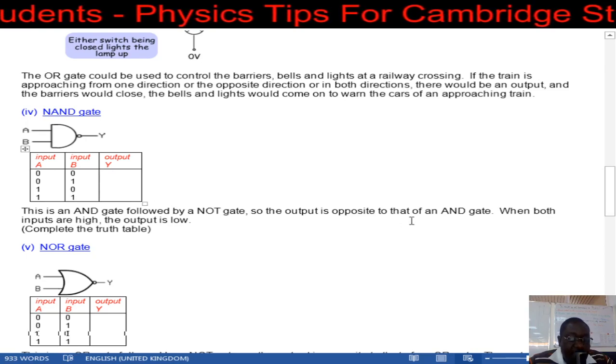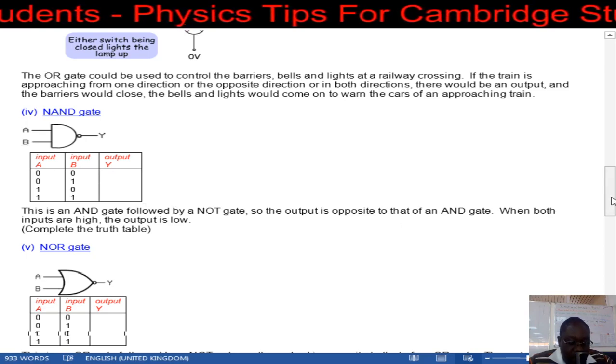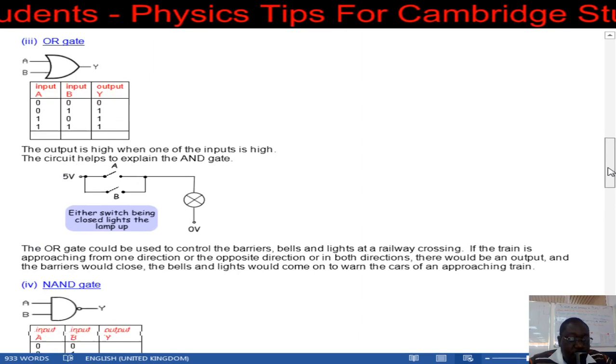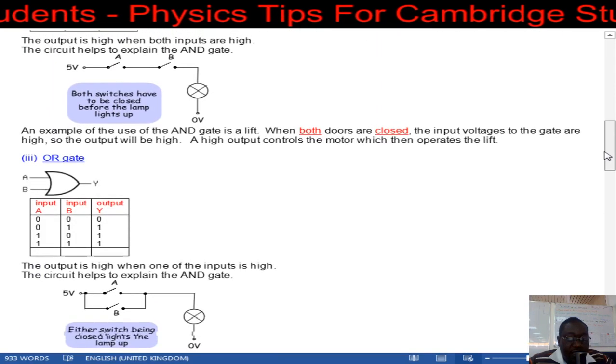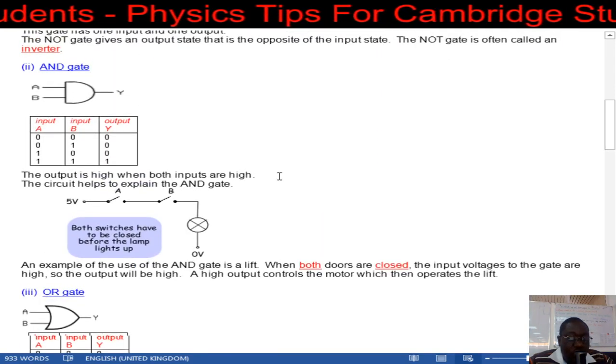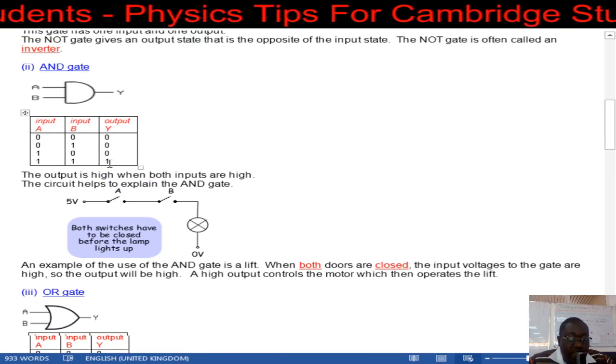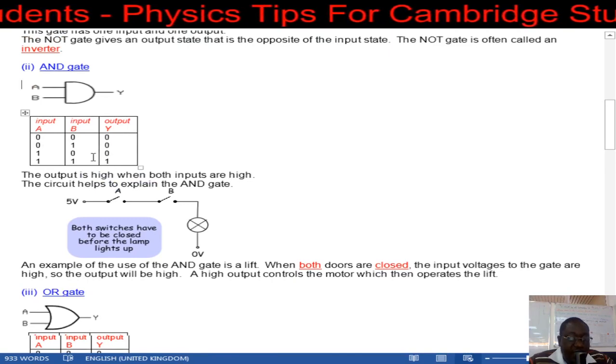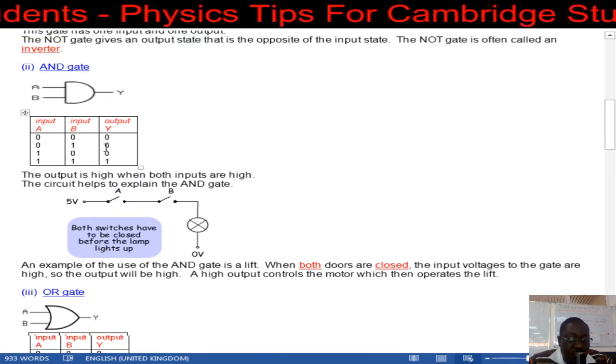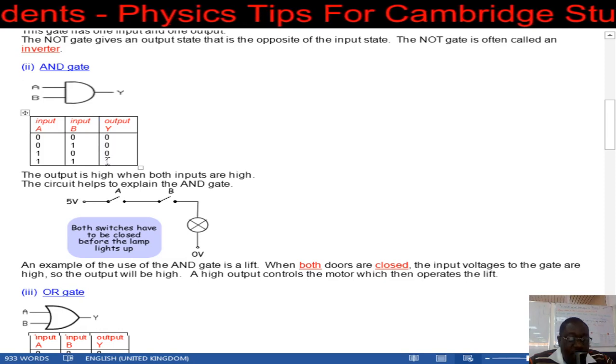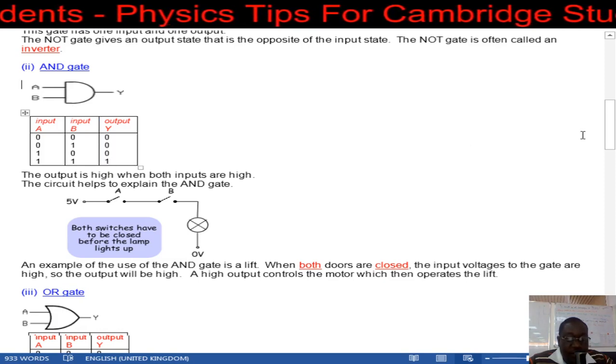Remember, in the AND gate, only the 1, 1 state was giving you a 1. In the AND gate over here, only a 1, 1 was giving a 1 there. So the NAND gate inverts this AND gate to give you 1s where there were zeros and 0 where there was a 1.